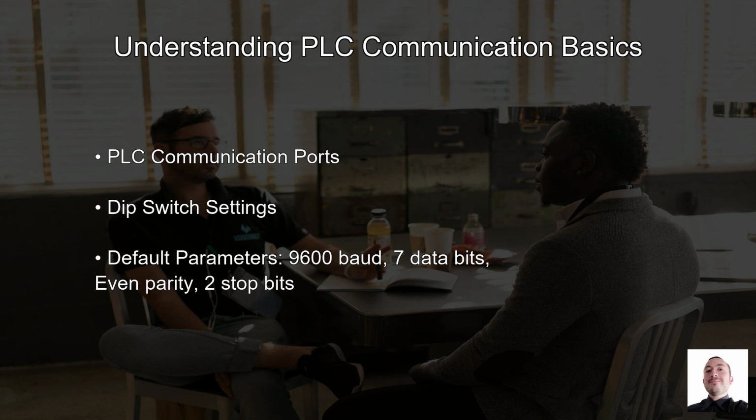for initial connections. Remember, the baud rate, parity, and other parameters must align between your PLC and the programming software to establish a stable connection. Misalignment here is a common pitfall, leading to communication failures. So, listen carefully as we unravel these critical components and settings, ensuring your PLC connections are seamless and efficient.